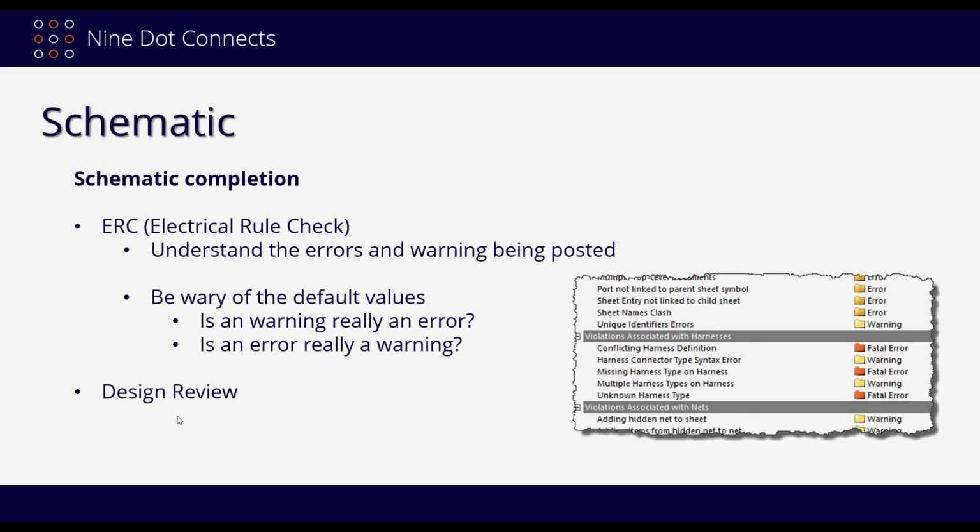The last thing is design review. Even though I just put this as one step over here, make sure you actually do a design review. Have a peer review, beat up on that thing, take a look at it, make sure it's ready to go before you move on. A lot of times we're like, good, you're done, move on to the next thing, and we almost entirely skip the design review, and obviously that's going to cause problems down the road. But the design review should also look at the requirements. Did you hit these requirements? That's why the requirements are important, because it's not just at the end when the product's built, it's at that stage where you're putting everything together in the schematics.